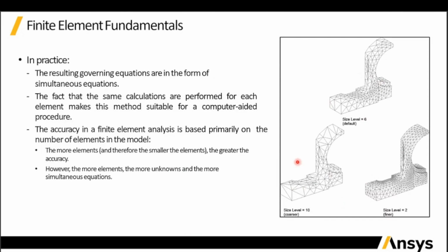Now, you learned that this is an approximate method. So how can I improve this approximation, or make the results closer to the accurate solution? The accuracy of finite element analysis is based primarily on the number of elements in the model.